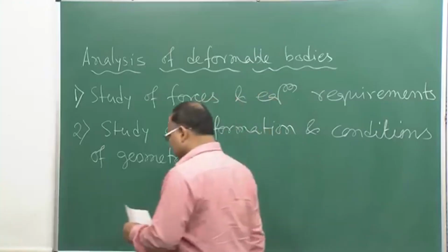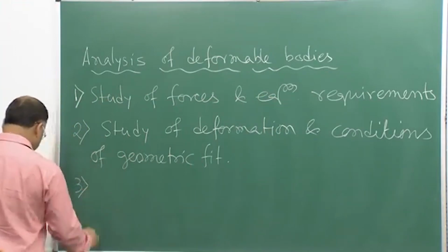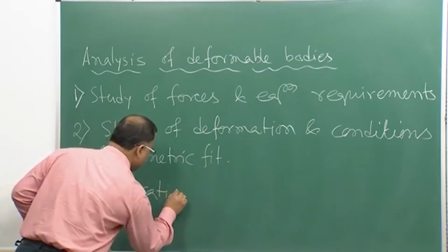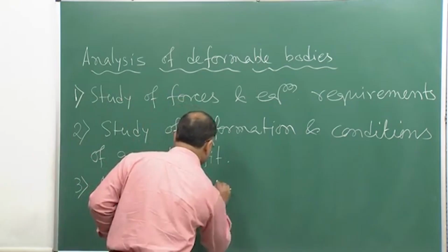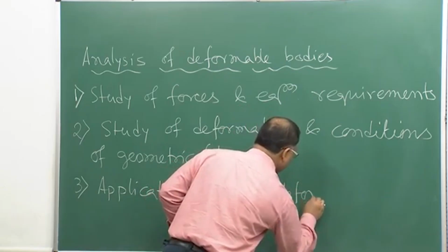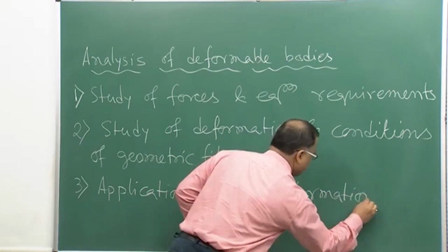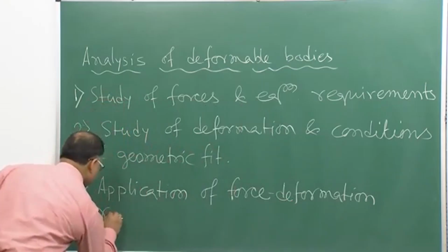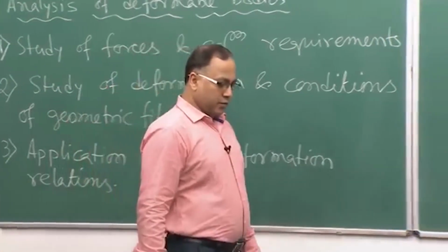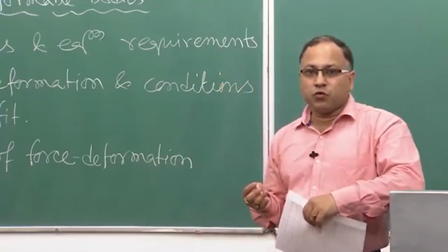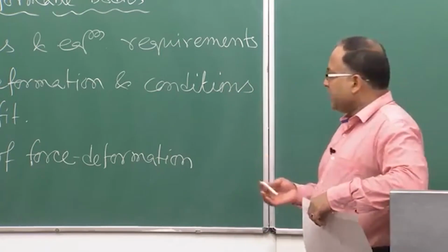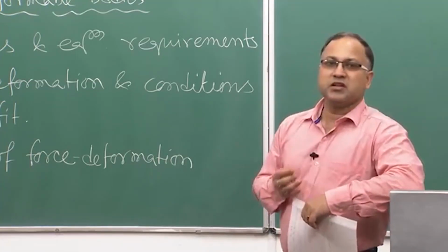Okay. Then the third step is application of force deformation relations. So, in the first step we are analyzing the forces, in the second step we are studying the deformation, and then in the third step we are applying the force deformation relation.